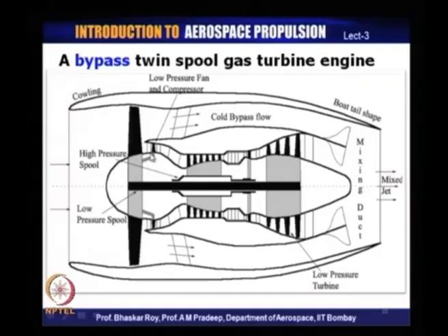And as a result of this independence of the two spools, the designer now has the flexibility to design the two spools in a manner such that they independently operate at their best and most efficient operating condition. One can well imagine, and as we go more and more, you would probably become familiar with these components, and you would realize that this independence is very important for operating each of them at their best efficient operating conditions.